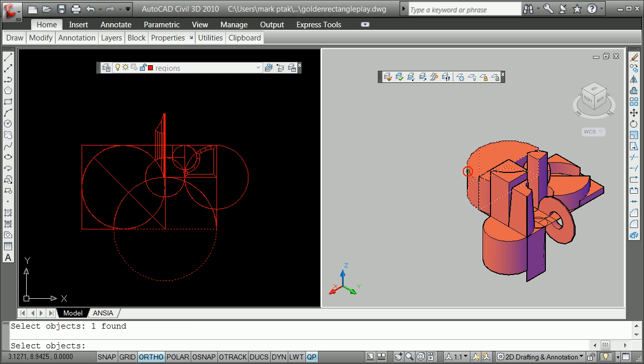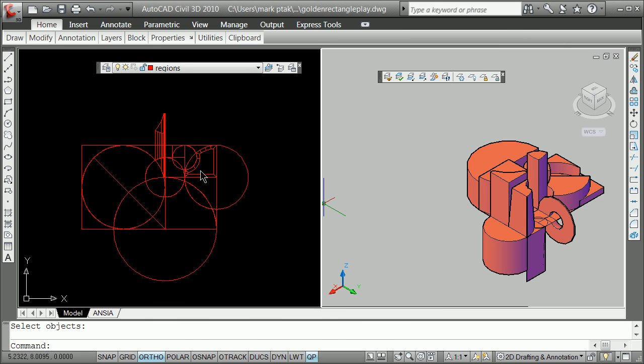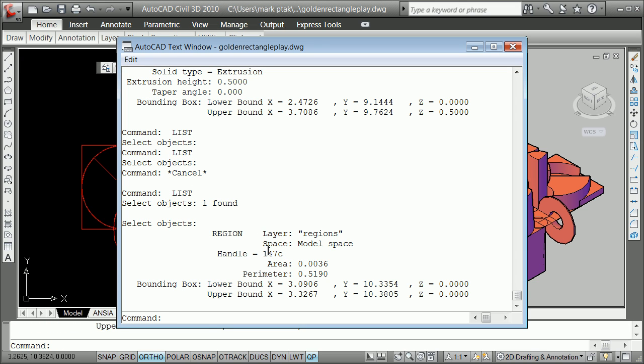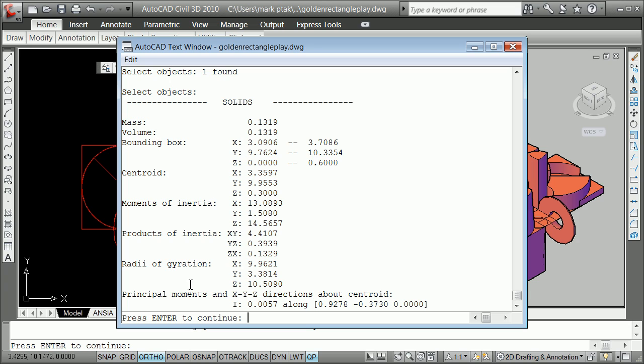I'm going to finish out the last 10 minutes looking around some commonalities here. That is a 3D solid list. Perhaps that is a region. We want to point out the idea of the lower boxes, but mostly the commonality of the interface, to say mass prop. So if I do mass prop on this thing there, I'm going to get a bunch of 3D coordinates and product of gyration, radius of gyration, centroids, bounding boxes, volume.